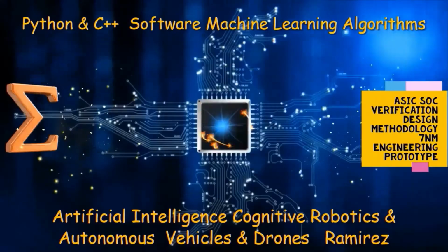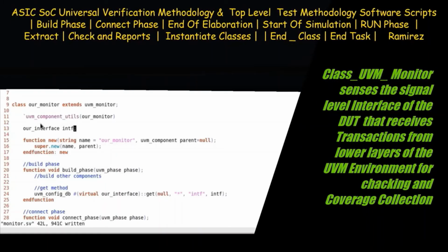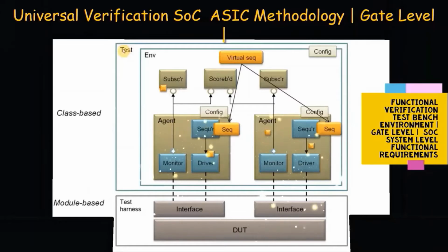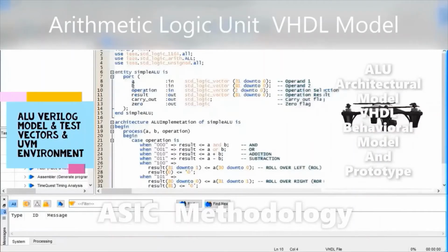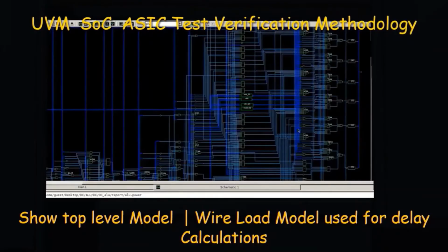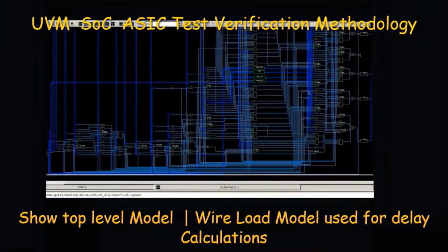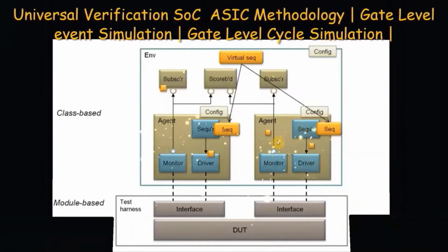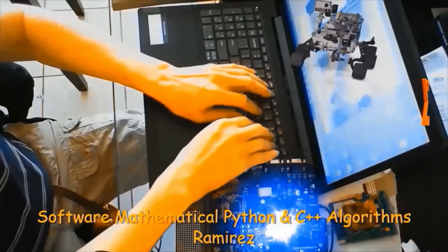So in order to accomplish this task, the code has to be structured into two separate domains: an untimed HVL domain that contains the UVM environment or verification environment, and which must not contain any delays or clocks; and an HDL domain that instantiates the DUT, the device under test, and the synthesizable parts of the transactors, which can be run entirely within the box.